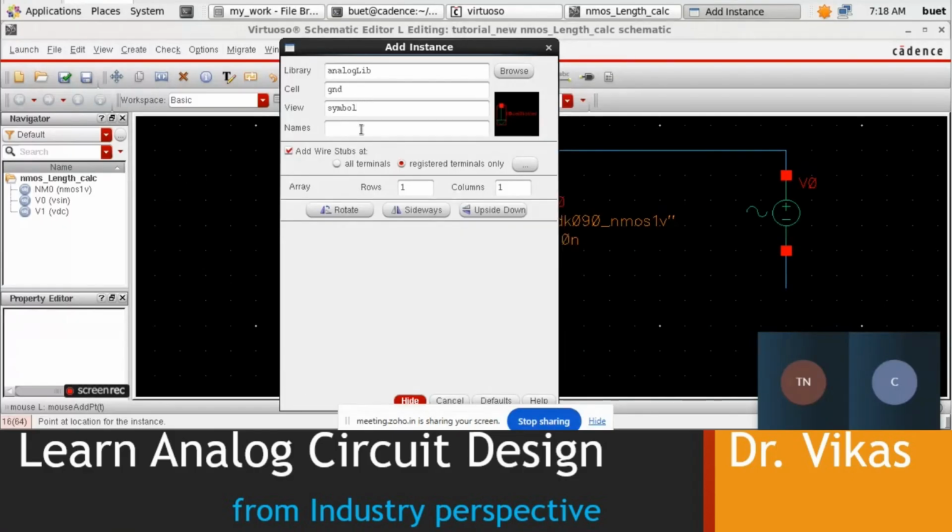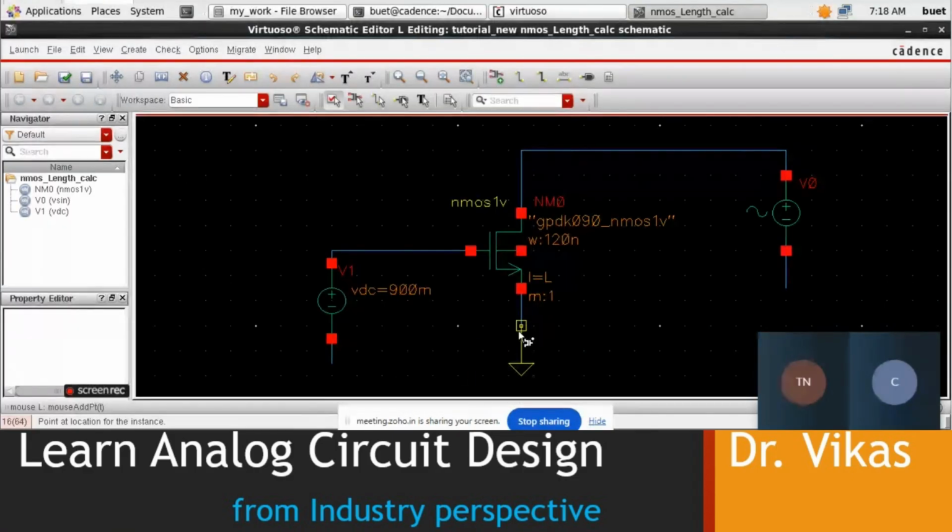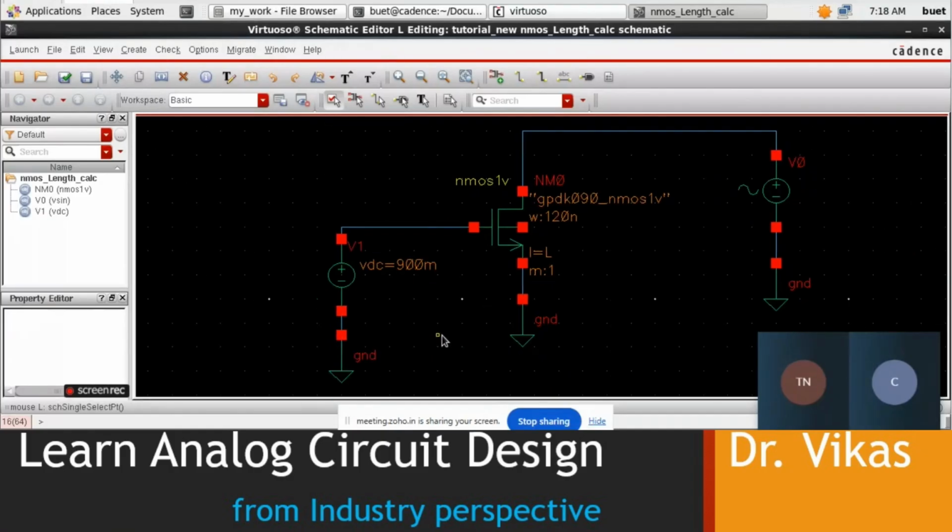And the best way to make sure the MOSFET enters the saturation region is to ensure that the output current, or the current flowing through the MOSFET, remains constant. That's how I can make my MOSFET stay in the saturation region. If I want to ensure that the MOSFET generates a constant current, then the best way to ensure biasing happens is to build a simple current source and attach it to my MOSFET. That means my MOSFET will always be giving the constant current.